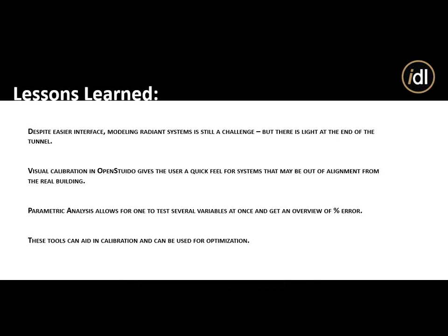Yeah, great question, something we've been dealing with a lot. It's very easy to export from OpenStudio to EnergyPlus. Coming back is a lot harder. You can get 90% of it, I'd say. You can get the geometry from EnergyPlus. You can get the schedules. You can get lighting and plug loads, but it really doesn't translate HVAC well.